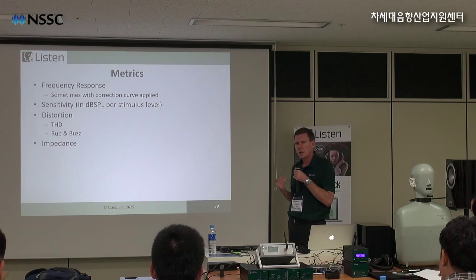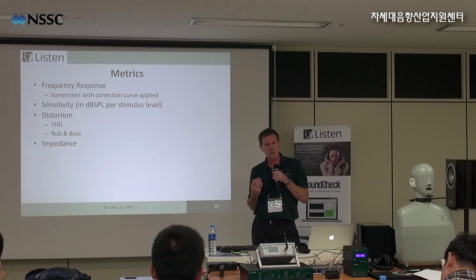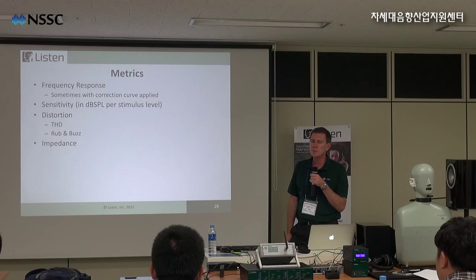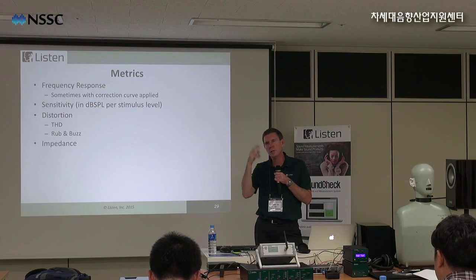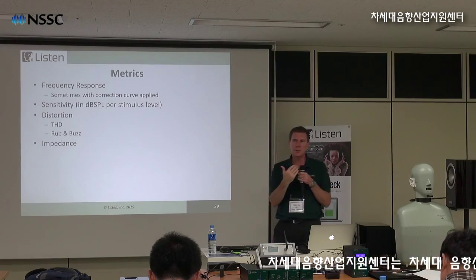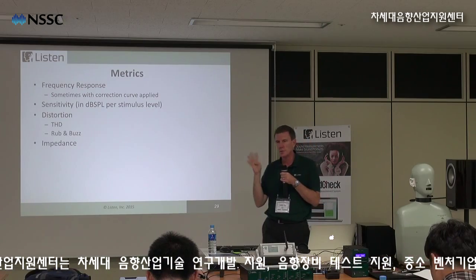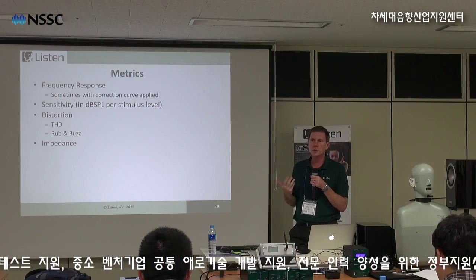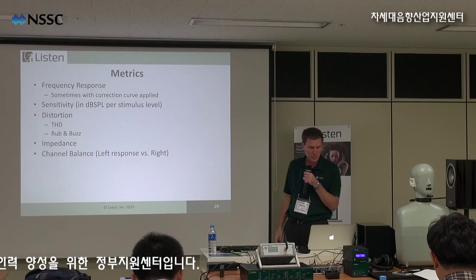Impedance. Not a lot of people measure impedance on headphones, which is kind of a shame, because just like with loudspeakers, it tells you quite a bit about the low frequency performance of the headphones. Typically in production, it's kind of a pain because instead of just 2 channels, one left acoustic, one right acoustic, you then have 2 impedance channels, left and right. So you need a 4-channel analyzer or audio interface. So you got to pay something for that. But for R&D, it's always a good idea to measure impedance. And if you want, you can even do Thiele-Small parameters.